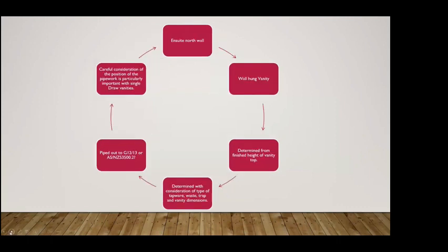Yeah, I did that. I had to connect the hot valve up to the isolation valves, and I accidentally put the cold to the hot. But once I did it, I was like, "Oh shit!" and I had to take it off. Usually it's not a big deal. But if you'd accidentally piped hot to the toilet, that's not quite so easy to fix. You'd actually have to work out where you can get back to the pipe, how you can rehook it into the right supply. Is anything else coming off that? Suddenly it's a much bigger problem.